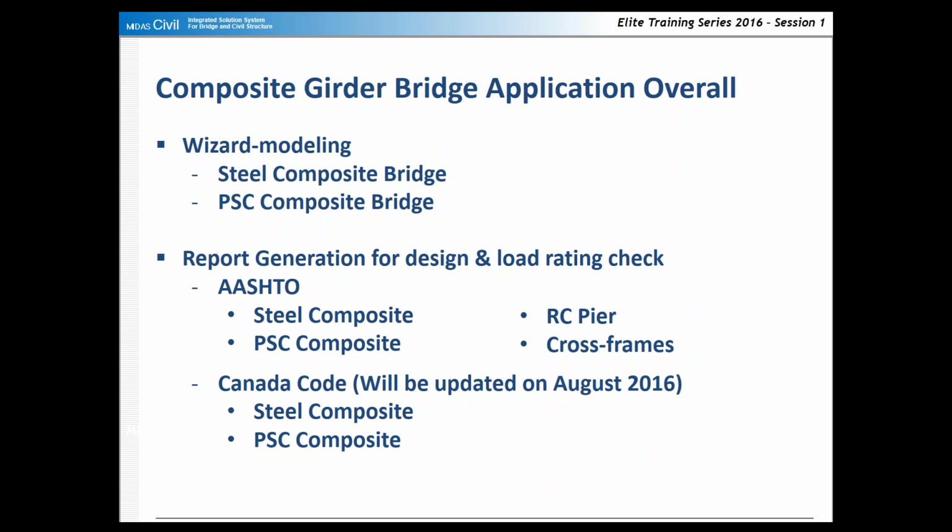What I'll be covering today, the wizard modeling approach, is not specific to pre-stressed concrete composite. I'll be briefly showing you the steel part too, but you can follow the same procedure for a steel composite bridge project. After modeling your structure using the wizard, for either steel or pre-stressed concrete composite, you can then move on to running analysis and generating the report for design and load rating check.